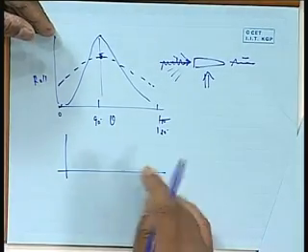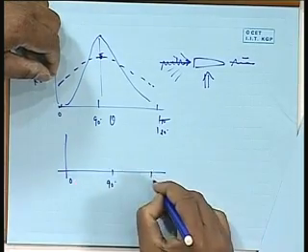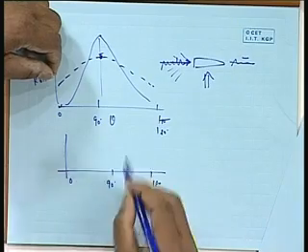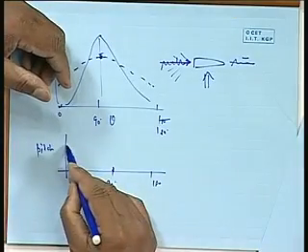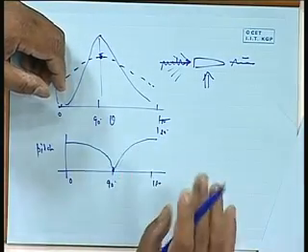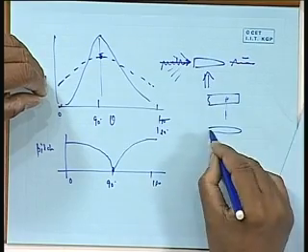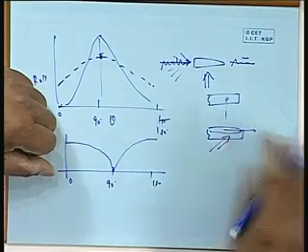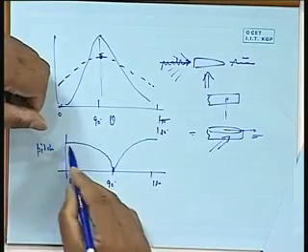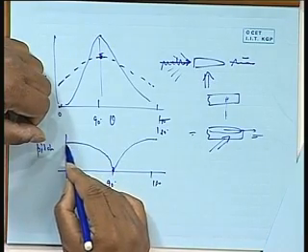Say pitch, for example, if you see the pitch here again, say this is 90, this is 0, this is 180. If you see pitch, you will find that at 90 degree, it doesn't pitch. So the graph will look something like that, and again something like that. Because at 90 degree, when the waves are coming beam, the ship does not pitch. When it is coming this side or that side, it pitches maximum. So it is maximum like that. But now if you take a three-dimensional spectrum, you will find that this will actually come down and be more spread.